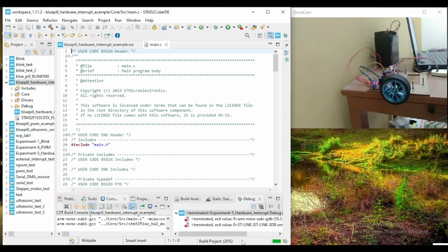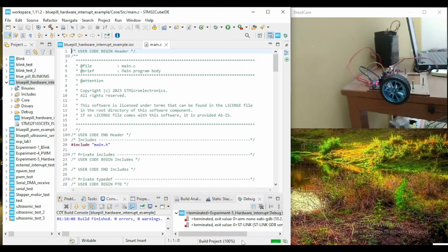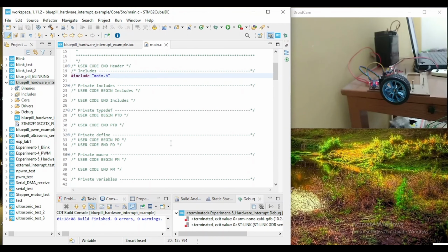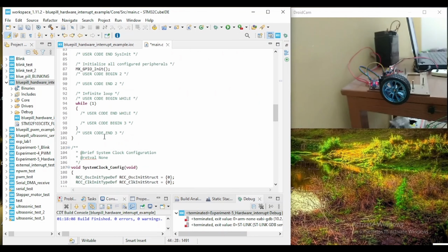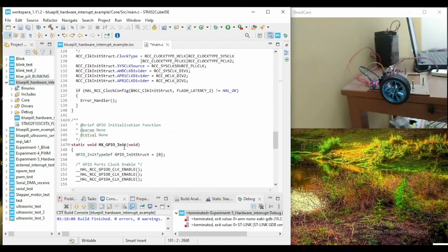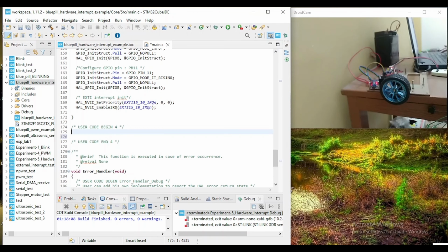In STM32, for protection of critical code section, we use interrupt masking. Here we have our code in which we are going to write volatile int32. The section of code is an STM32 HAL-based GPIO interrupt program using PB10, PB11. The volatile int32_t steps equals 0. int32 is a 32-bit signed integer ranging from -2147483648 to the positive 2147483647.